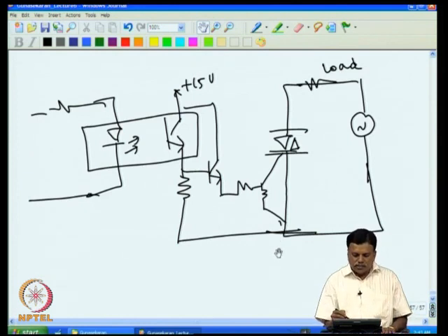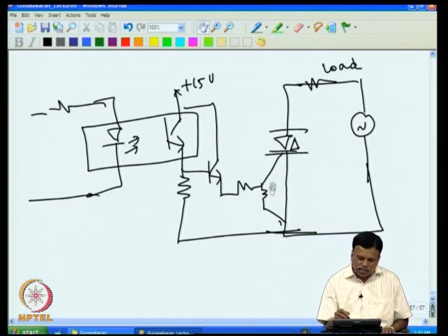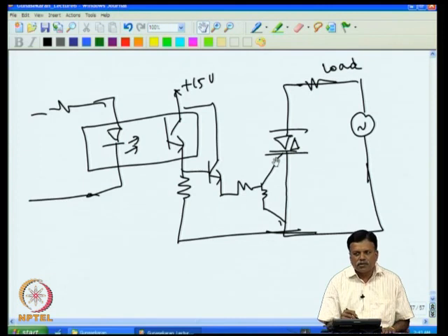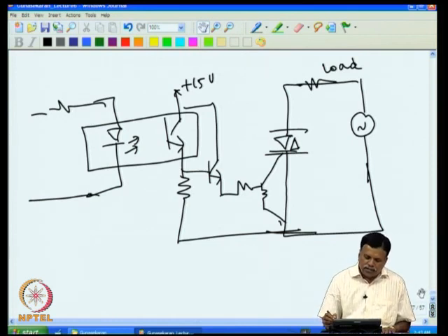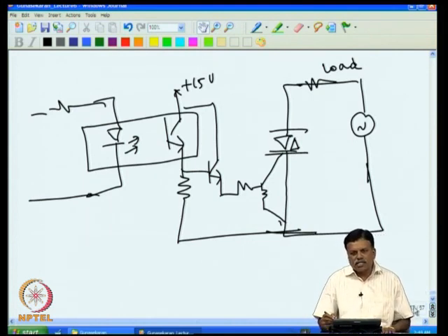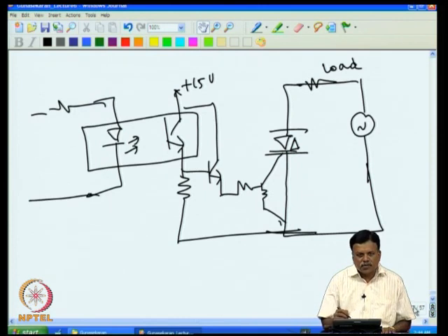Now the circuit can also be further improved in the sense that we can make the triac fire only at zero crossing. That is also possible. That we will discuss probably in the other part, when we are using a drive for a proportional controller. So for an on-off controller, these are the different possibilities of driving the heater voltage. This is mainly to practice the formation of different circuits, because one has to acquire circuit design skill only in smaller steps by seeing how each step is followed.